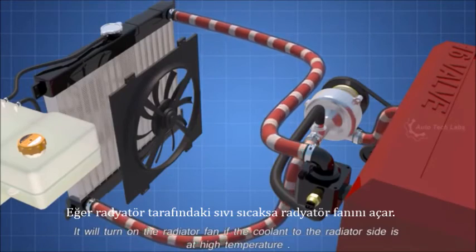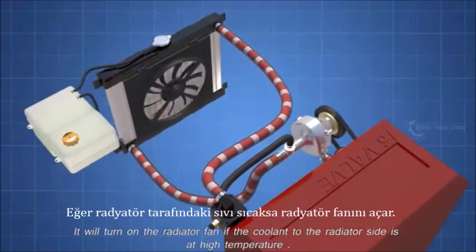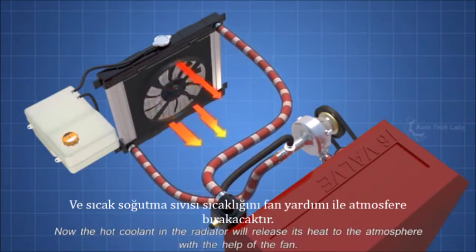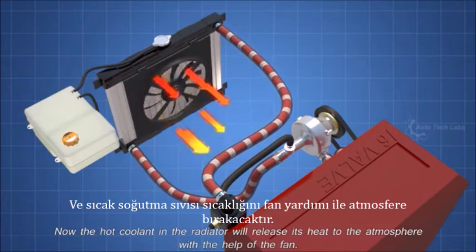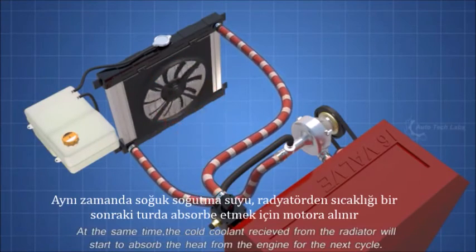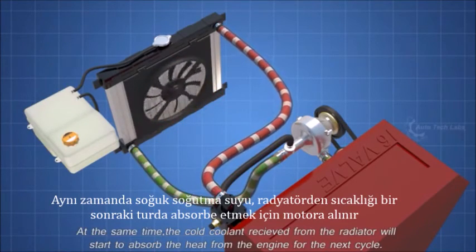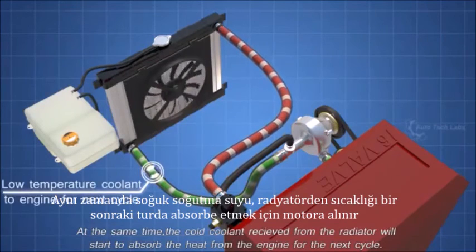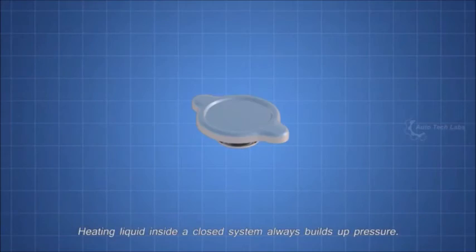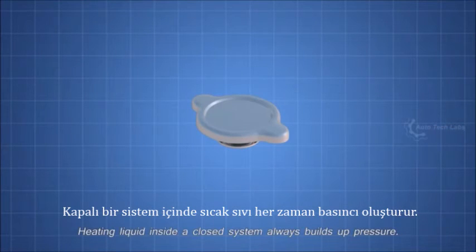It will turn on the radiator fan if the coolant to the radiator side is at high temperature. Now, the hot coolant in the radiator will release its heat to the atmosphere with the help of the fan. At the same time, the cold coolant received from the radiator will start to absorb the heat from the engine for the next cycle. Heating liquid inside a closed system always builds up pressure.